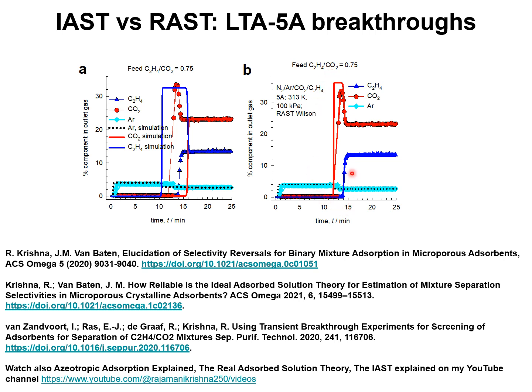The breakthrough experiments can be reproduced by the RAST, but not by the IAST. This underscores once more the strong non-idealities that are inherent for CO2 capture with cation exchanged adsorbents.